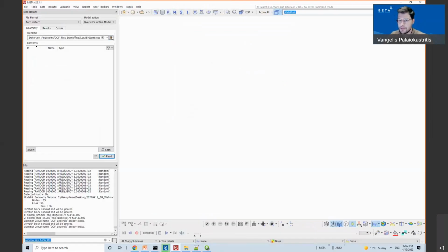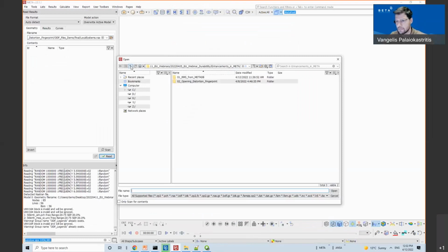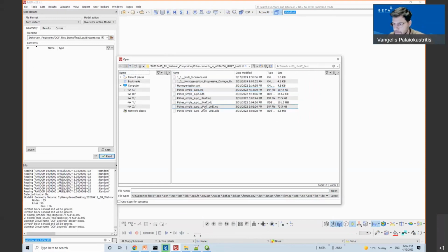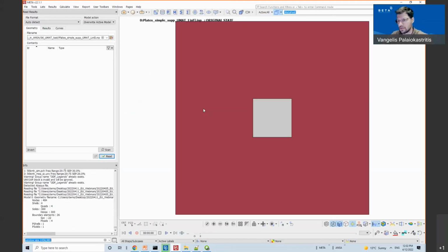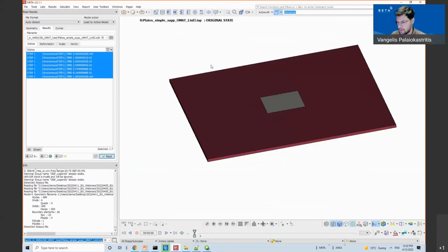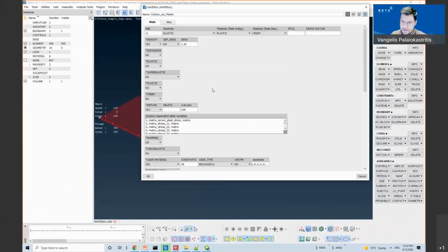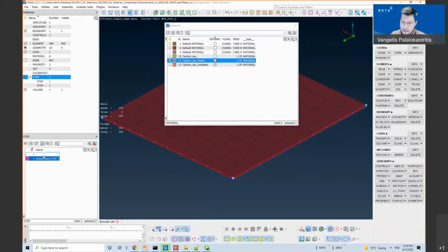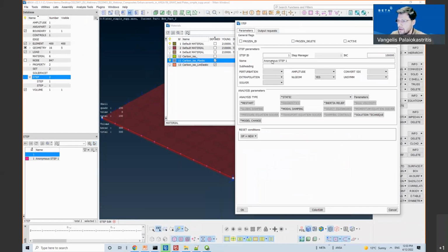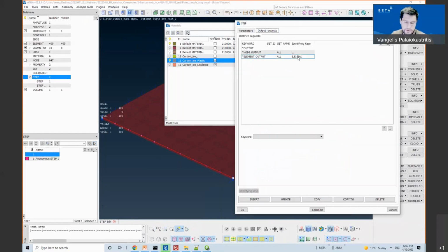If we go in Meta, now, if we output this model with the UMAT material that has been assigned to the solid elements, and if we also have the SDV output requests, we will get the results of the UMAT subroutine.